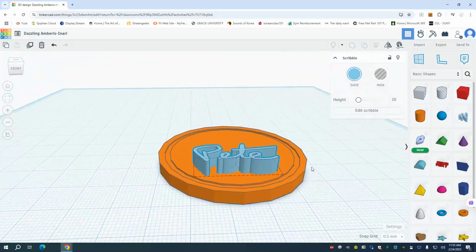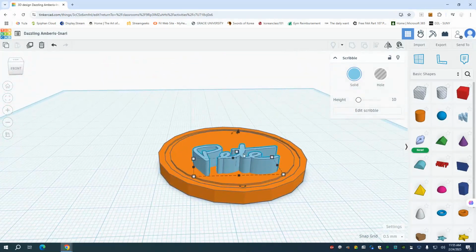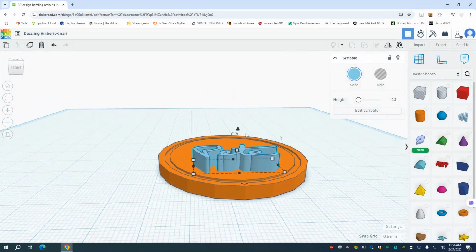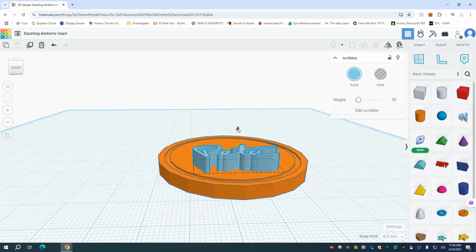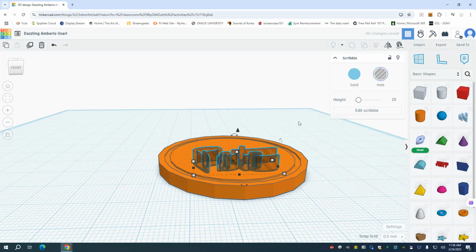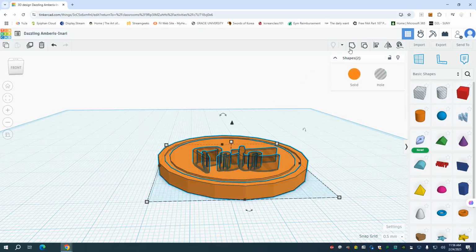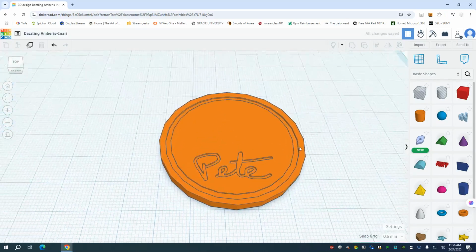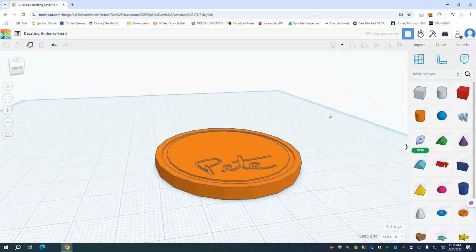So once you've scaled it and placed it, you're going to use that drop arrow and drop it down a 0.5 millimeter. So it should be 3.5 millimeters. And I want this as a whole, right? Negative space. And then I'm going to select everything and say group. And what that'll do is that will make the negative space.